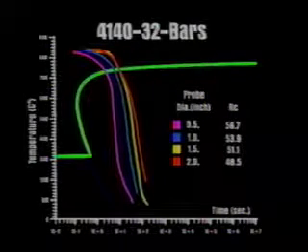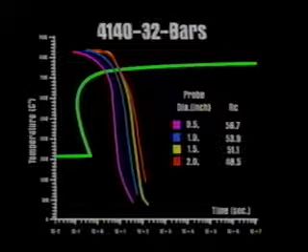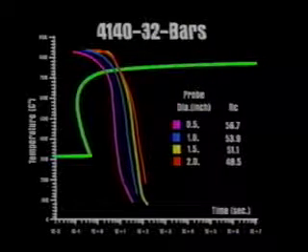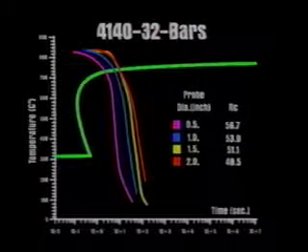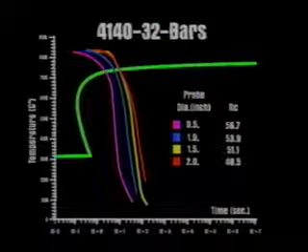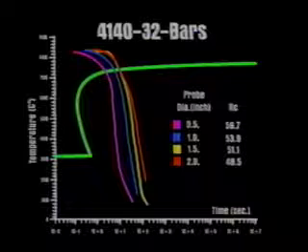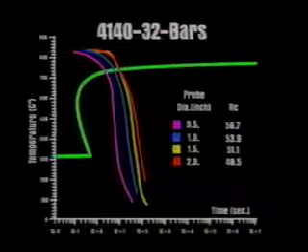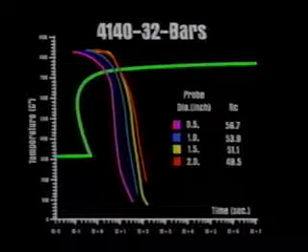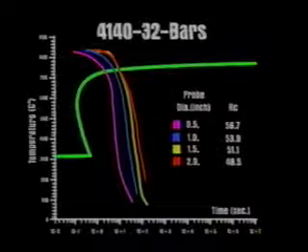And also for cooling curves for a 20% concentration of a polymer quenchant at 60 degrees Celsius, 140 degrees Fahrenheit, superimposed on a transformation diagram for AISI 4140 steel. In both cases, hardness decreases as cross-section sizes of the bar increases from 1/2 to 1 to 1 1/2 to 2 inches. In addition to cross-section size, the shape of the component being quenched must also be considered.